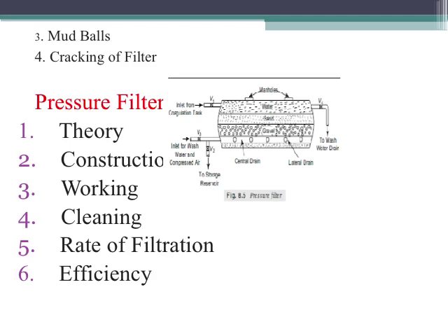So now about the cracking of filters. The finer sand in the top layers of the filter bed starts shrinking, and this causes the development of shrinkage cracks in the sand bed. These cracks are more prominent near the junctions, that is, on the walls.